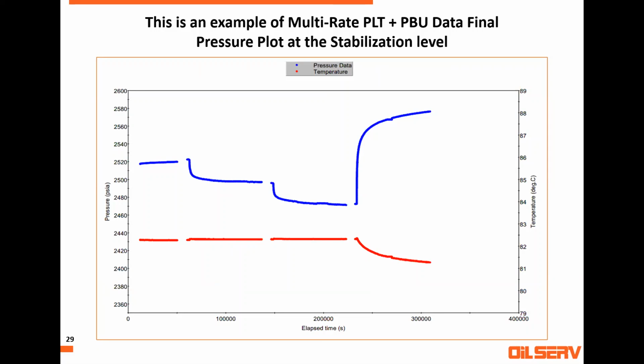Some companies want 1 PSI, 2 PSI per each 2 hours. Some companies say 10 PSI is good for me, each 2 hours or each last 1 hour. I have faced some company in South Iraq that asked us to wait 18 hours till the well gets stabilized before they do PLT passes. Some of them just use the standard, wait 2 hours, do your PLT. So there is a reason to call it stabilization.